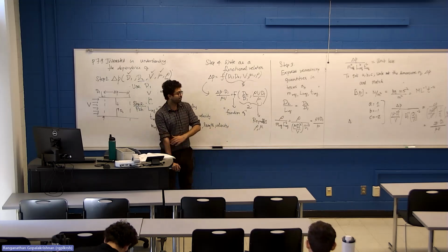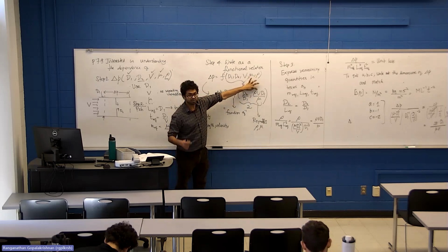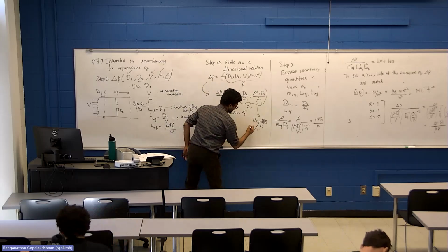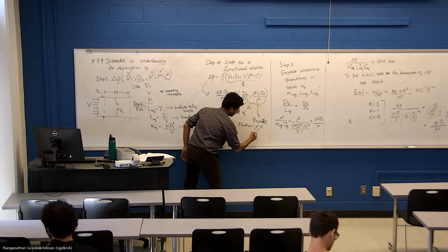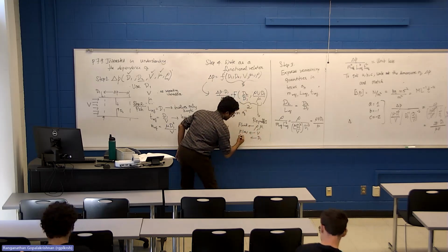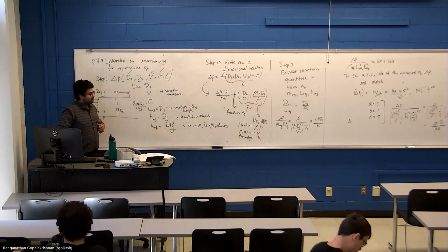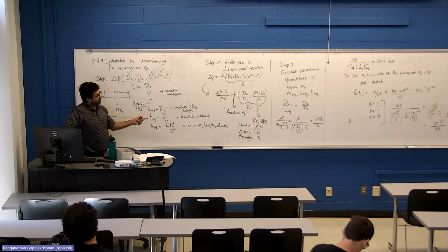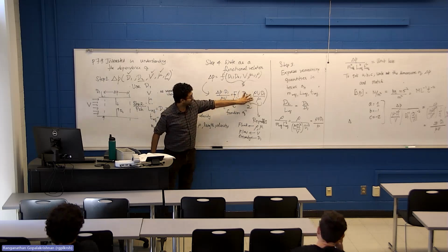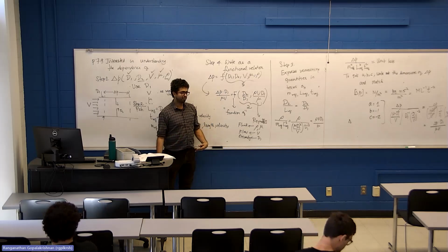It depends on density and viscosity, which are fluid properties, on the velocity, which is a flow property, and on diameter, which is geometry. So it's a combination of all three. We'll see pipe flow and flow over a sphere, examples that prove Reynolds number will show up every time you analyze a fluid problem, pretty much.